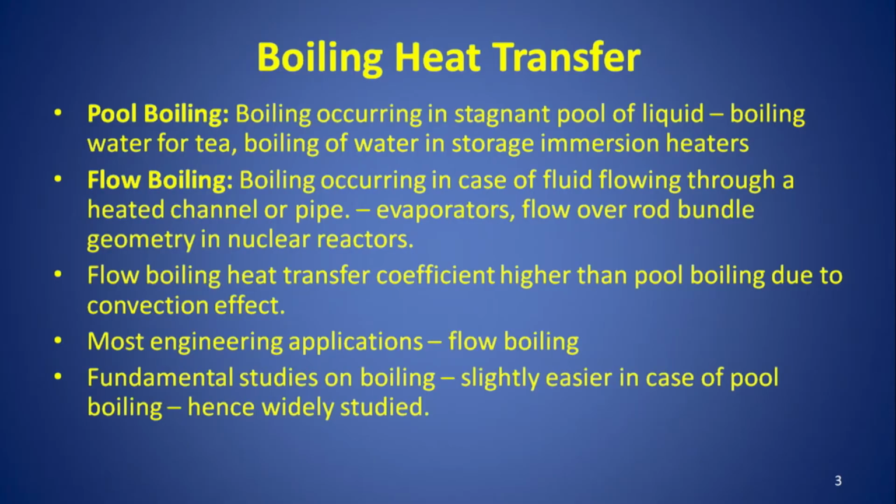Then why do we study pool boiling? Pool boiling is very important because it involves one less variable which causes a lot of difficulty in analysis, and that is flow. The fluid mechanics of flowing water is a lot more difficult than a stagnant pool. And when we talk of boiling, the primary reason why boiling is so much better compared to single phase heat transfer is the removal of the latent heat. So, for the same temperature difference, you get a higher heat transfer coefficient.